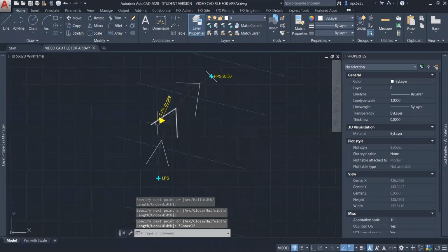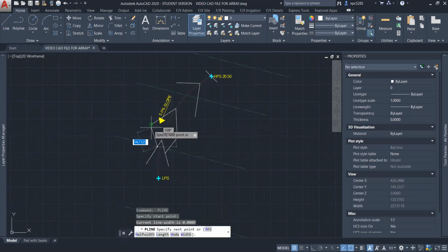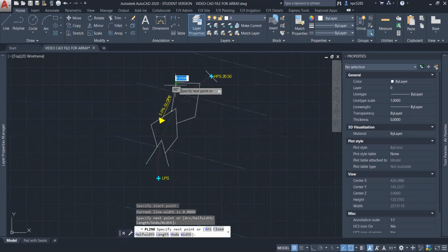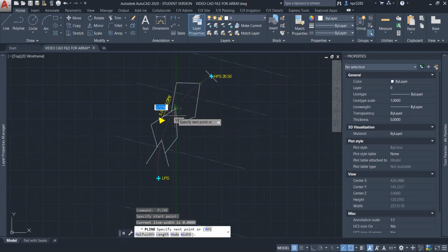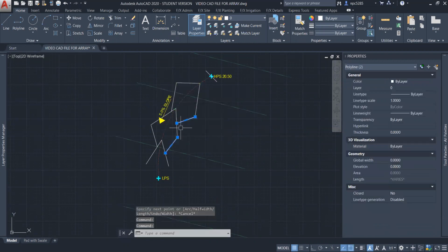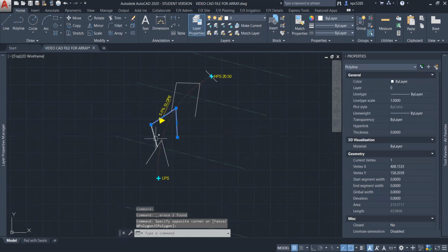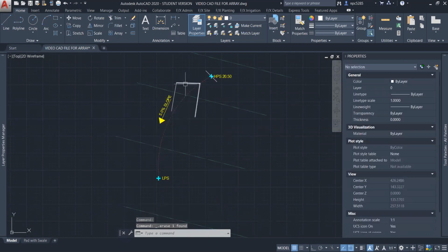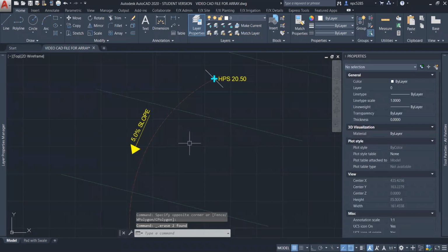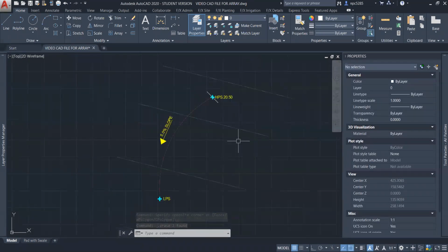So what's important is that this stays uniform and that the gap between here and here, here and here, that this length becomes uniform, as well as the distance from here to here along the center line of the swale. So I like to either make a tick mark initially at the top or bottom that I'm going to be measuring along. And the command that you use is array.